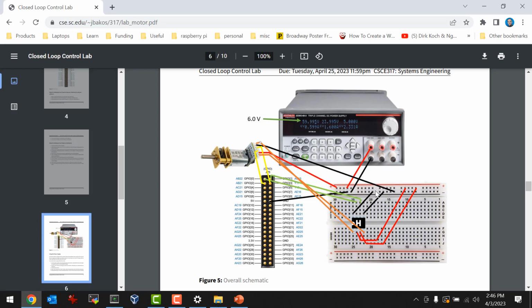So you stick it there on the breadboard, and then you just have to connect. There are two VDDs on there, two power pins that you connect back up to your plus rail here. And there are two grounds that you connect to ground.